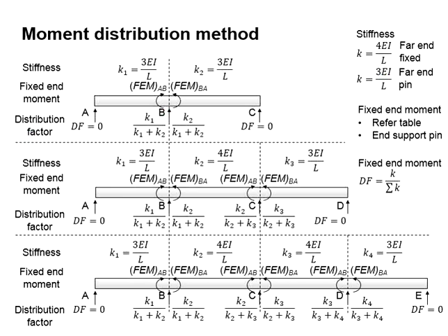Now you will need to first know the purpose of determining the stiffness. The stiffness is used for you to determine the distribution factors. You are making relative comparisons of the stiffness between two stretches of the beam meeting at a joint. The higher the stiffness, the larger the moment the beam will be taking. The quantum of the moments to be taken by different members will be identical to the percentage of the stiffness of that particular stretch out of the total stiffness at the joint.